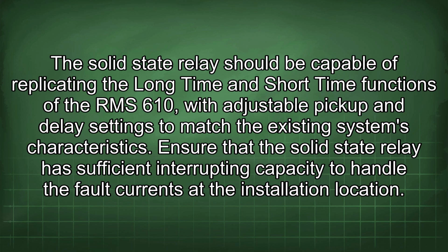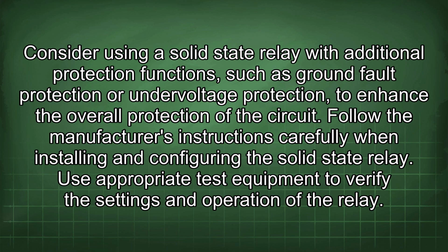Ensure that the solid-state relay has sufficient interrupting capacity to handle the fault currents at the installation location. Consider using a solid-state relay with additional protection functions, such as ground fault protection or undervoltage protection, to enhance the overall protection of the circuit.